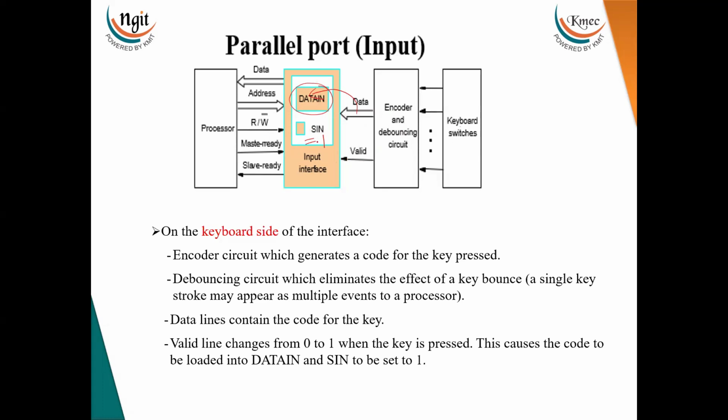So if it is filled, the status bit will show 1. The SIN bit is one of the bits of the status register. Now, whenever the processor wants to read data from the data in register, the processor first always reads the status of the interface register.